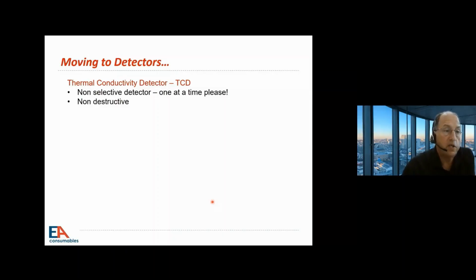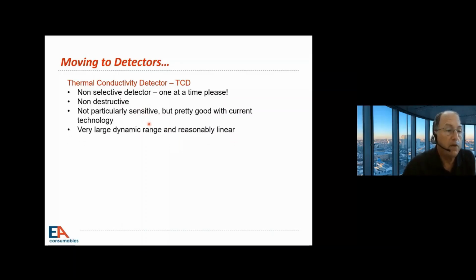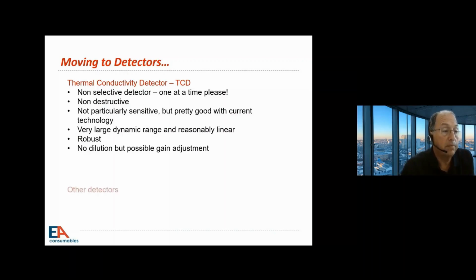They're non-destructive, which is really good in case you want to put a second detector afterwards or do isotopic analysis of the gas. They're not particularly sensitive, but they're pretty good with the current technology. Very large dynamic range, they're reasonably linear, and they're robust. Dilution's not possible, but we can alter gain electronically in order to get things on scale.